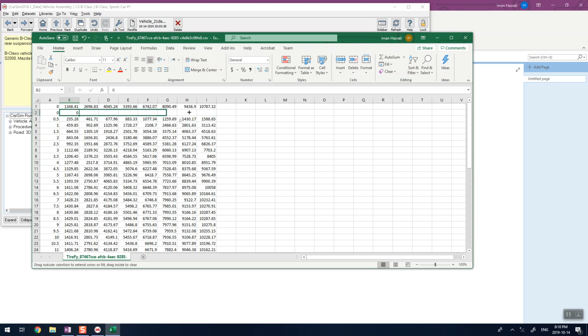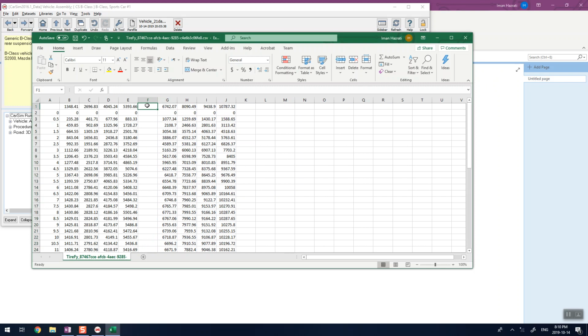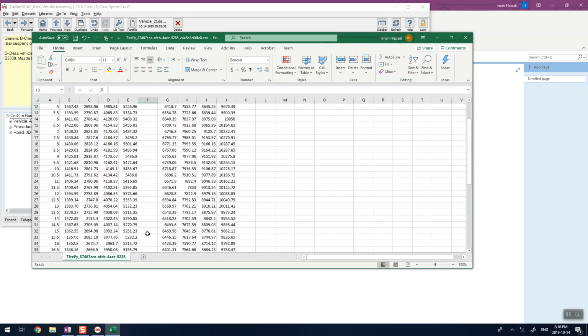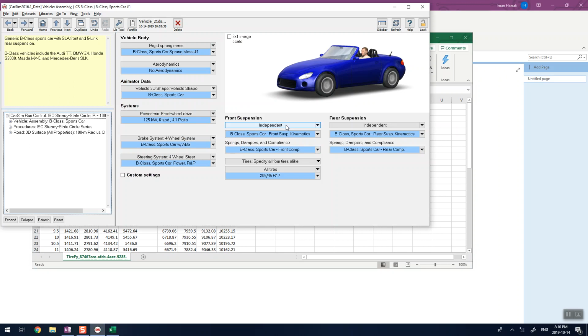So let's say what we have based on the load, you will have a load here with something around, let's say, I don't yet calculate it, Newton for one tire in front and differently in rear, and you interpolate between these two values, a linear interpolation, to find it. There are some codes in MATLAB, in Excel to find it for you. So when you have a force, you try to find the C alpha. C alpha is linear, and you should know what's the linear range of the force. But anyway, for now, I think that's enough.